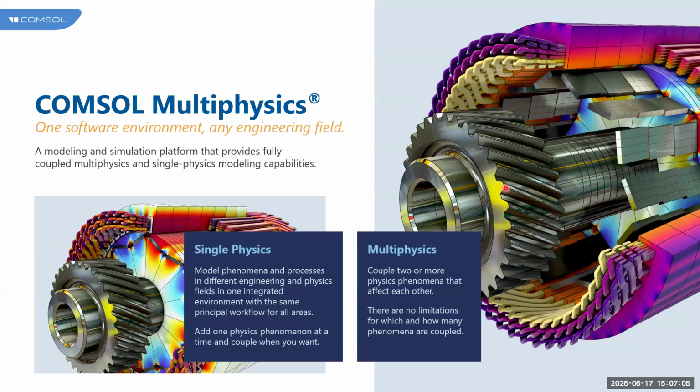And sometimes you might be interested in evaluating the radiated noise out from the machinery as well. So COMSOL is a unified platform where you can couple your electromagnetic physics with heat transfer, structural mechanics, and acoustics, and solve for all the characteristic performances of a single operating machinery in a single GUI. And the workflow that you are going to use for different physics is going to remain the same.